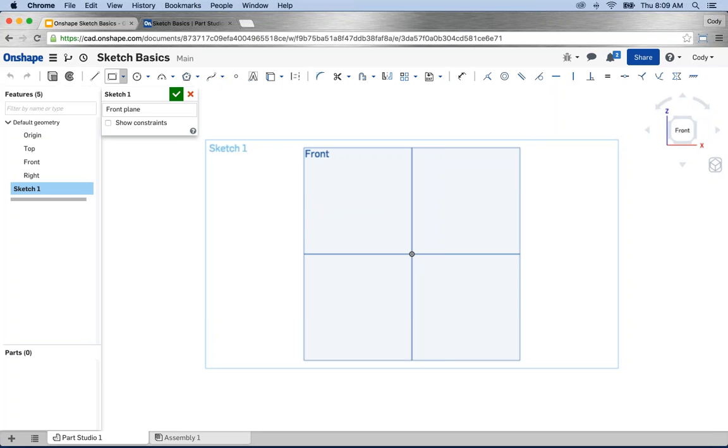So I want to start with a line. I'll select line, left click, and move my cursor down. Notice the cursor changes from an arrow to a crosshair, indicating that you're in a tool. Now I want to draw a simple line. There are actually 2 ways to draw a line. If you've come from a traditional CAD system, this is very similar. You can do 2 left clicks or a left click and drag. I'm going to show you both methods.